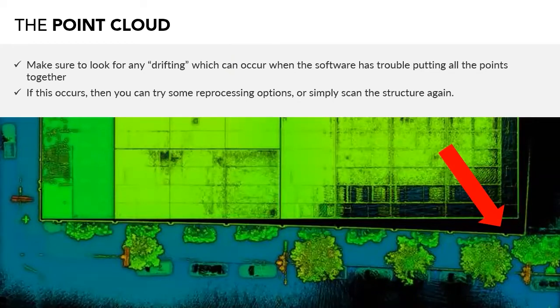So in this instance, in the photo on the slide, the surveyor wasn't able to walk a full loop or traverse around the entire building to help the algorithm lock in the accurate perimeter. And you can identify that by seeing that kind of big dark spot on the right side in the point cloud data. That just shows that there wasn't really any data there and helps us understand that that was what was causing this drift. So determining the reason for the error is crucial to informing your decision on how best to reprocess or potentially even rescan your project.